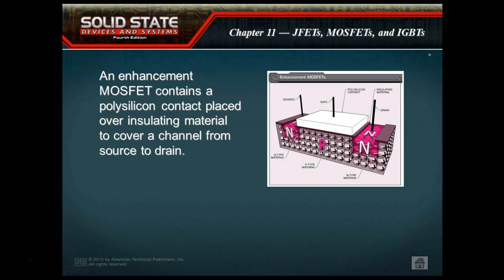It's nothing but silicon oxide, which is a very good insulator. Then the substrate material is just what we mount the channel into. Then we have our base. Now what we have here is we don't have a channel. So an enhancement mode MOSFET or eMOSFET has no channel until you create one. And how do you think you create one? Well, you create one by putting a DC charge on the gate.